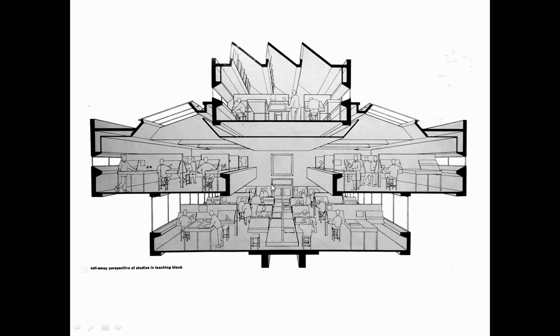As I said to you before, there are big reinforced concrete shear walls every so often along the length of the building, and these are bridges. They are a cross section. This is a beam that's doing that job of spanning from this wall to the one on this side. This is doing the same. So these are all beams of one kind or another. Continuous cross section, reinforced concrete in this case. And of course you won't see it in this drawing, but linking these underneath are a series of little drop-in concrete beams that link the two together to make the overall structure work.